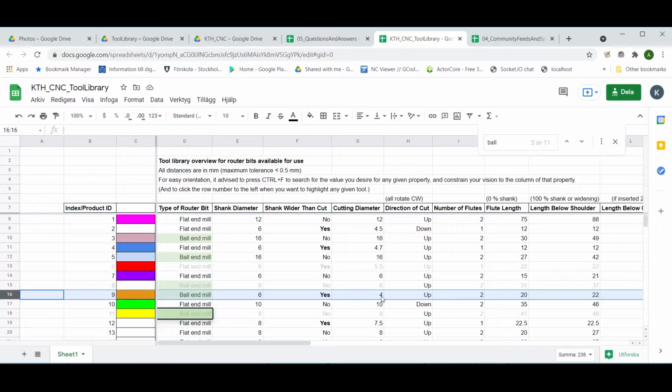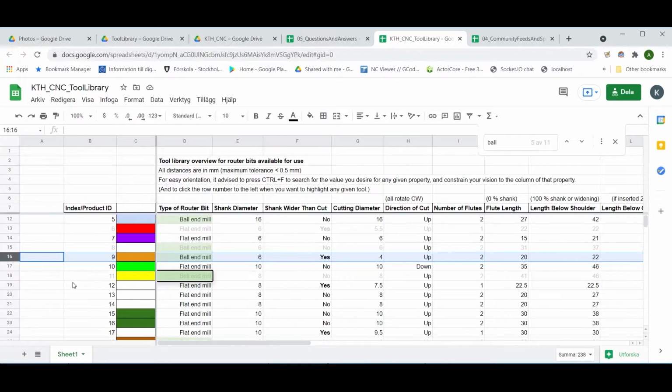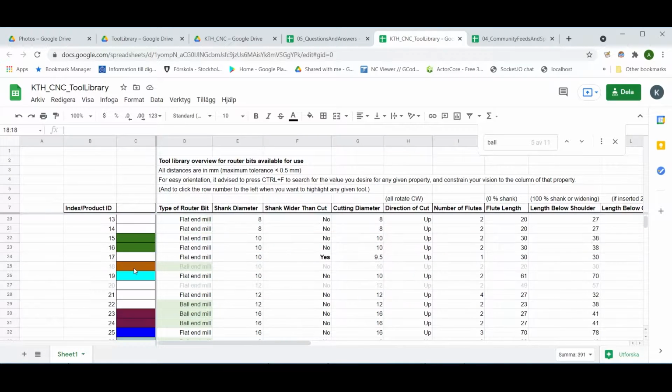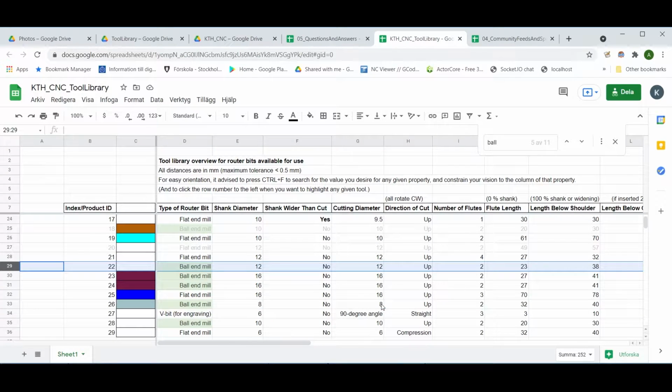And thus it is a wise move to use a finishing toolpath tool diameter of the same or marginally lower diameter than the roughing toolpath. This of course depends on the actual geometry that you're milling, but generally one should be aware of that. Alright, and this one is decommissioned, as well as this one. Here we have 12mm, which is even wider, and these are 16.